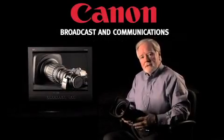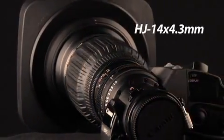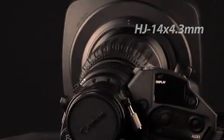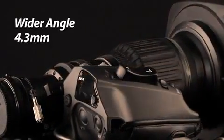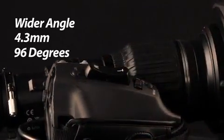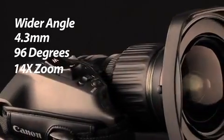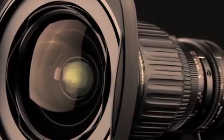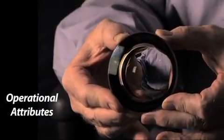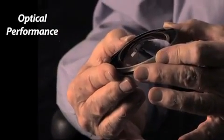The new lens that I'm going to describe is an HJ 14 by 4.3 millimeter. So it's a wider angle, being 4.3 millimeter, a wide angle of about 96 degrees, and a 14 times zoom. Now, there are two primary design goals behind this lens. One is the operational attributes of the lens, and then very important, the optical performance of the lens.